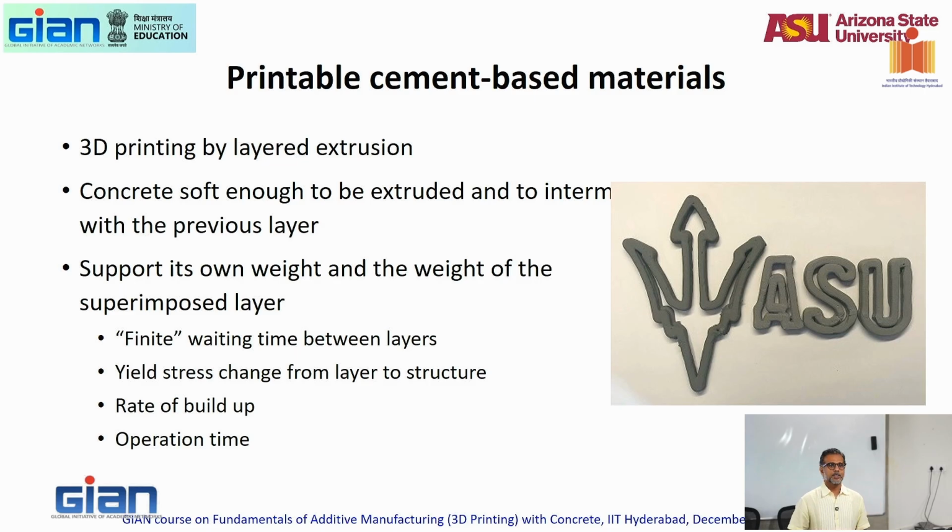Yeah, it was a concrete foundation. So foundation is all done. It's all concrete mat foundation. So just a concrete mat. In Arizona, because of the type of the soil, you always need a post tension foundation. So it is always a standard way that you need foundations for that. So it's all post tensioned.